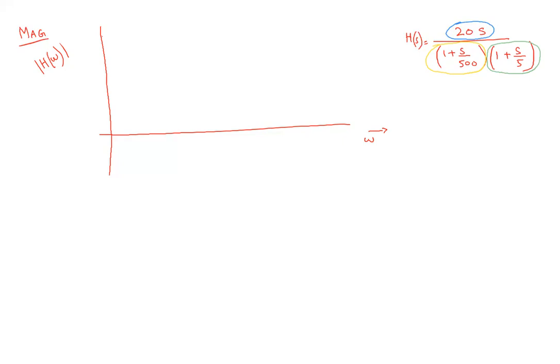But we know at a very low frequency, it's a zero. This means it's going to be on the rise, so a positive slope, with 20 dB per decade. But interestingly, we don't know the initial or starting value. But we have one piece of information for the zero, that at s equal to 1, we know the magnitude value. If we only consider the zero initially, we're going to see one by one.